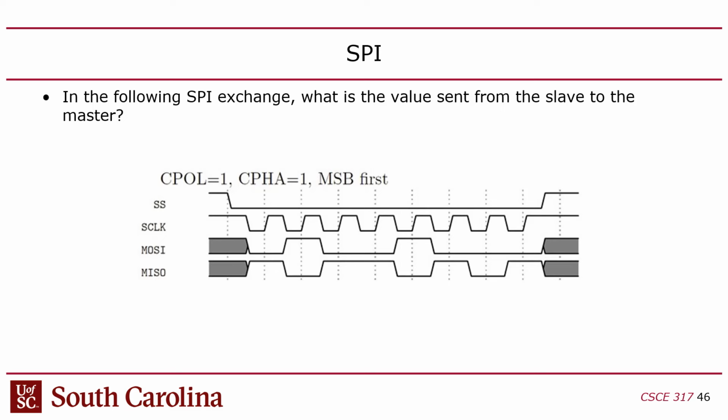And so in a flip-flop, you have this thing called setup and hold time. You have to have the data established on the input of the flip-flop for the setup time, and you have to hold it for the hold time relative to the clock edge, right? So what that means is that this allows us to have the data set up one half cycle earlier, and it's held for a half cycle later. If you violate that and you try to read the data on the same edge the data is changing, the risk is you violate setup and hold time on your flip-flop, and that causes the flip-flops to become metastable. They go into metastability, which means that the flip-flops will sample a halfway signal between 0 and 1. Now, they'll eventually correct themselves, but in the meantime, you're going to potentially get some corrupted data. Does that make sense? So the objective is, whenever you look at the edge of the clock, the data should be read a half cycle after the data changes, which should also then correspond to the clock edge, right?